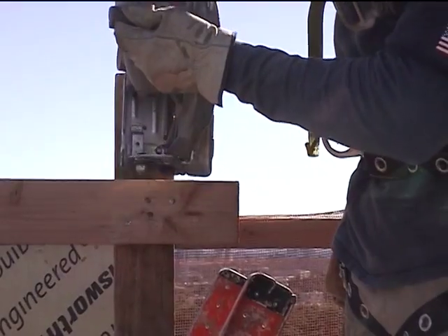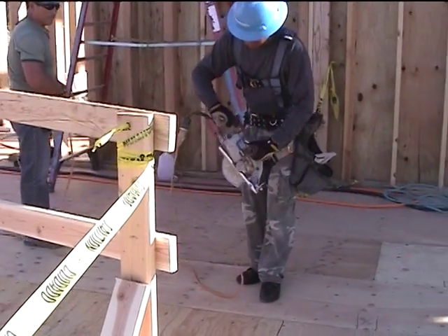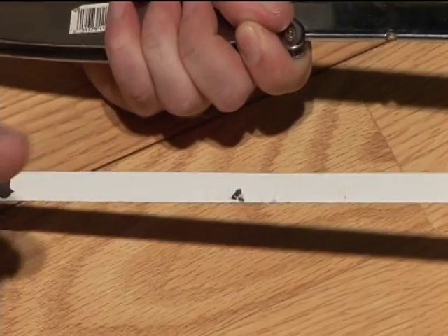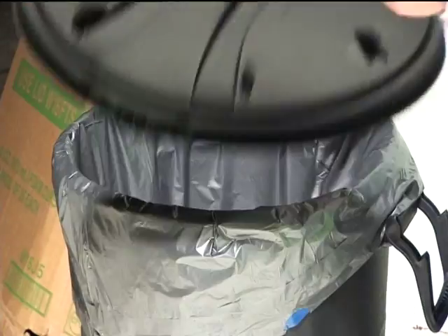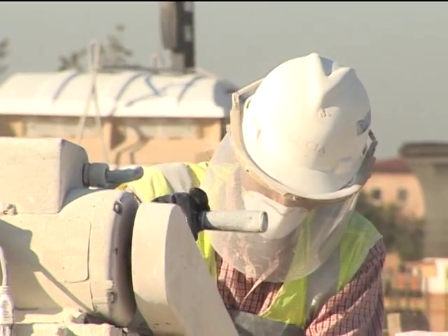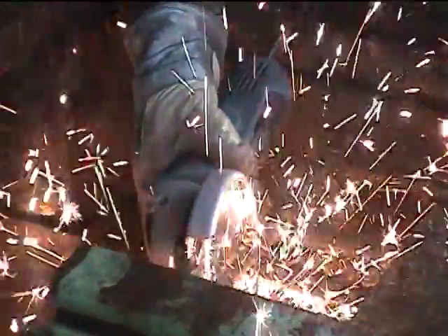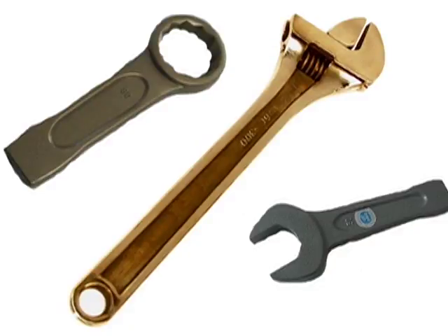Saw blades, knives, or other tools should be directed away from an aisle area and other people working in close proximity. Always keep knives, scissors, and other blades sharp. Dull blades are more dangerous than sharp blades. Cracked saw blades must be removed from use and discarded. Always wear appropriate PPE, such as safety goggles and gloves, to prevent injuries and accidents when using hand tools. Iron and steel hand tools can produce sparks that can be an ignition source around flammable substances. Use spark-resistant tools made from brass, plastic, aluminum, or other non-ferrous materials in explosive or hazardous atmospheres.